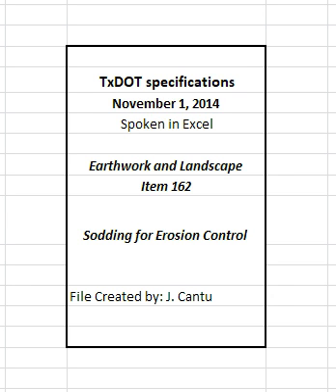3.1.3 Mulch sodding. Mow sod source to no shorter than 4 inches, rake, and remove cuttings. Disc the sod in 2 directions, cutting the sod to a minimum of 4 inches. Excavate the sod material to a depth of no more than 6 inches. Keep excavated material moist or it will be rejected.